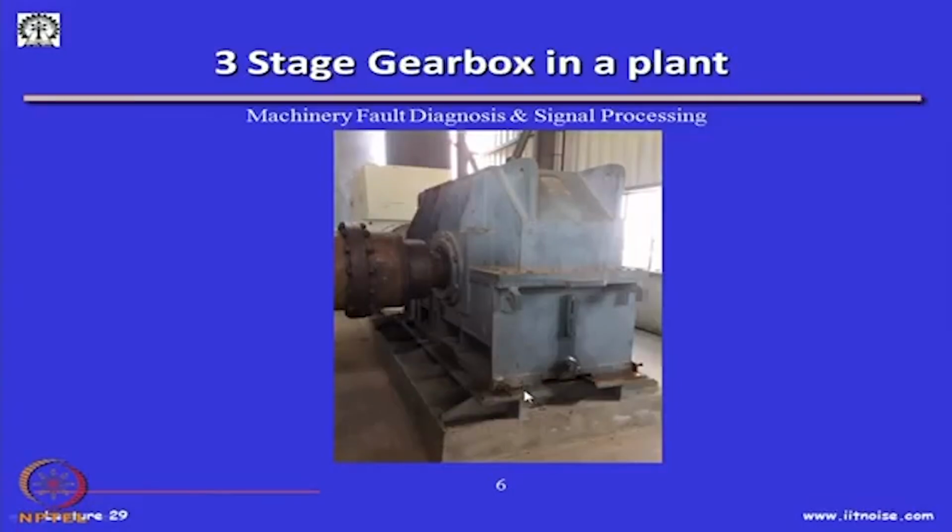Poor manufacturing of the gearbox housing, poor foundation, harsh environments, these all lead to the misalignment of the gearbox base, which in turn will increase the load, because there are heavy bearings here. There are usually rolling element bearings at this location, and these bearings will be responsible for the unnecessary loads on the shaft here, and then there will be uneven wear.